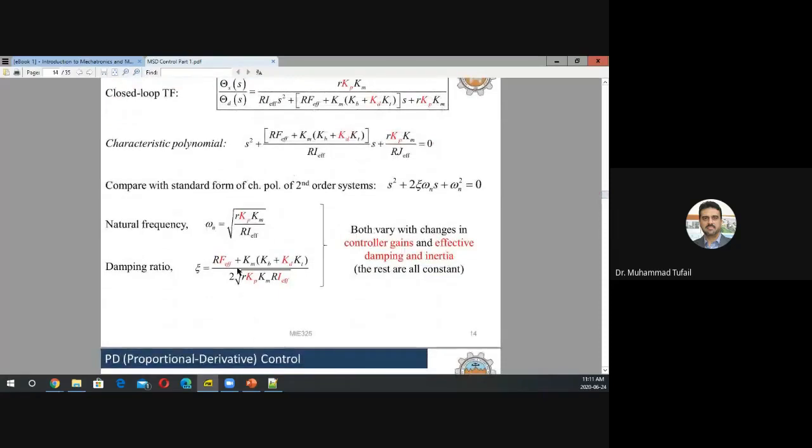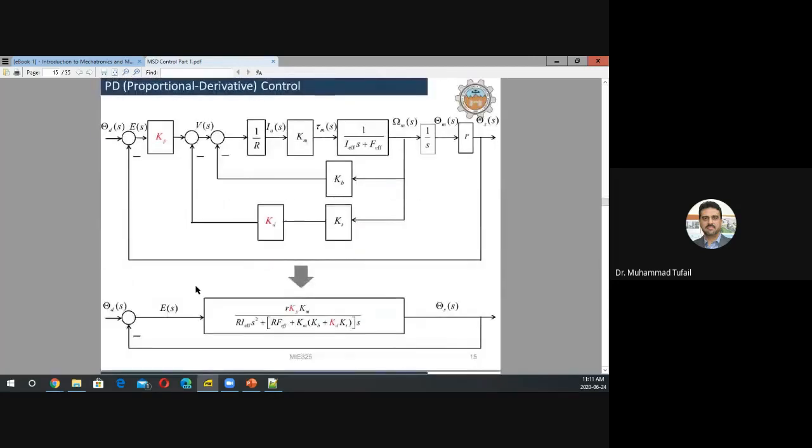لیکن میں نے یہاں پہ آپ کو یہ بتانے کی کوشش کی ہے کہ Kp changes brings the vibrations in the system. ٹھیک ہے. Kp makes the system under damped. Kd kills vibrations in the system. It increases the damping of the system.